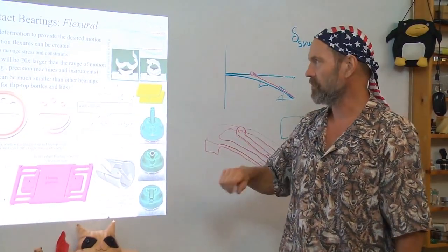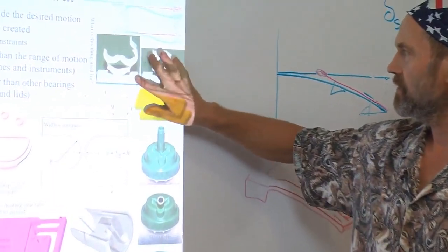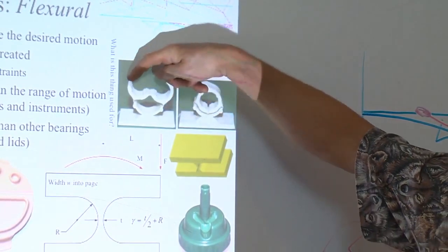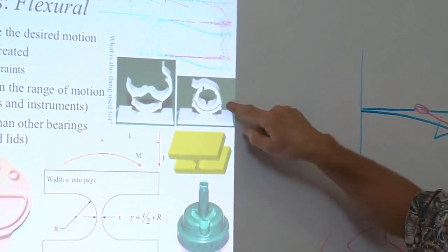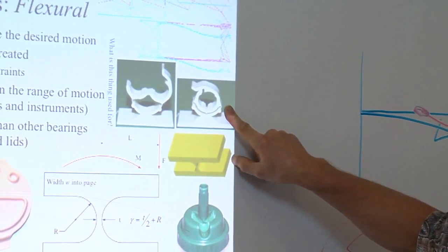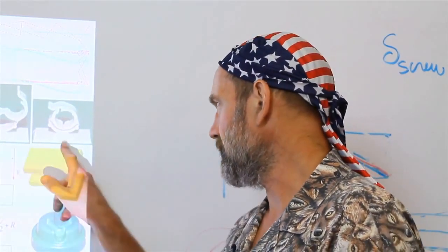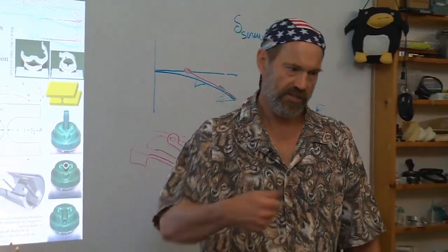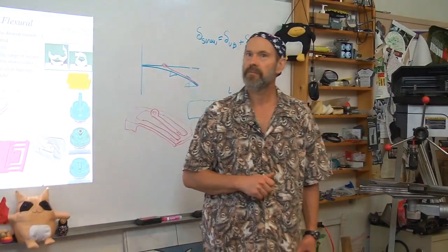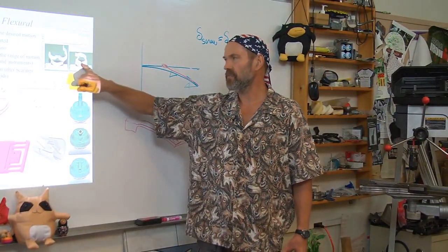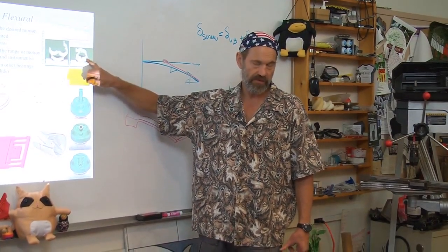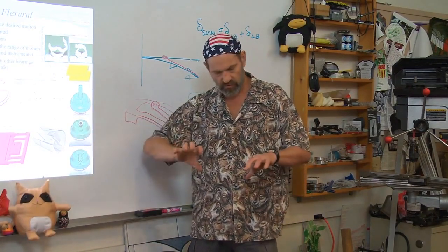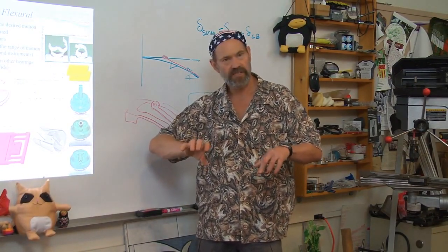The other thing to note about flexural bearings with respect to consumer products that you may design, and even industrial products, is, for example, here is a structure that's all injection molded. It clamps over and then snaps closed with a snap connect, and this is for holding cable bundles. With these adhesive elements, you adhere it down on your machine, lay your cable bundles in it, and then just snap, snap, snap, snap. So the bearing has a large range of motion, but only applied for just a couple cycles. Lids for drink containers are another example, as are rotary flexural bearings, often called C-flex couplings.